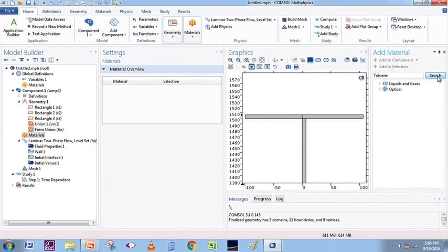It builds a set of matrices of our governing partial differential equations and tries to solve it in one go. There are three different direct solvers available in COMSOL Multiphysics. One is PARDISO, which stands for parallel direct solver, MUMPS for massively parallel multifrontal direct solver, then SPOOLES, sparse object oriented direct matrix solver. These three actually, the MUMPS solver can do cluster computing. It divides its work into many nodes as the case may be, and searches for the solution.